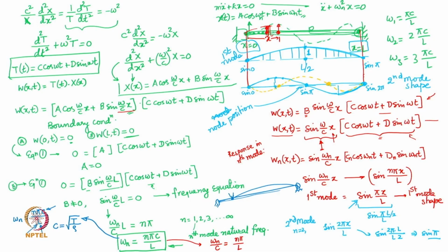So if you want to play the strings generating sounds of different pitch value, you basically start reducing the effective length of the string, and you can see that reducing the length of the string is going to again increase the natural frequency of the string.